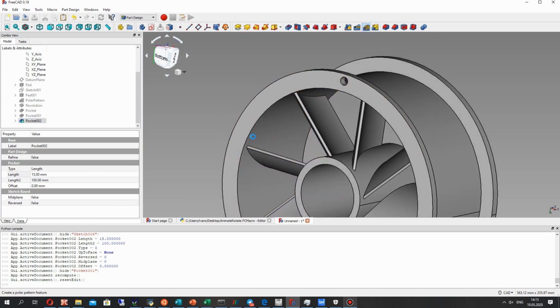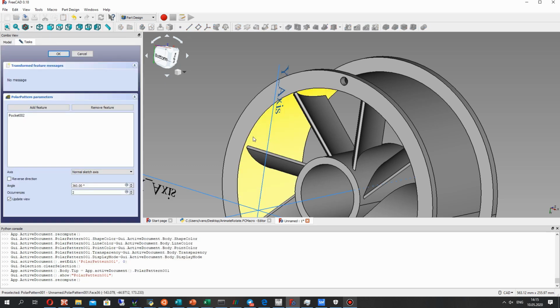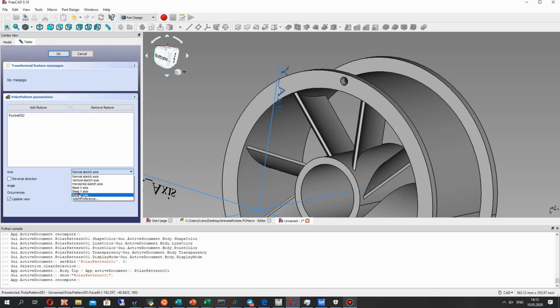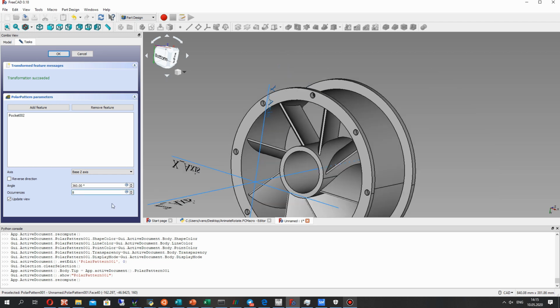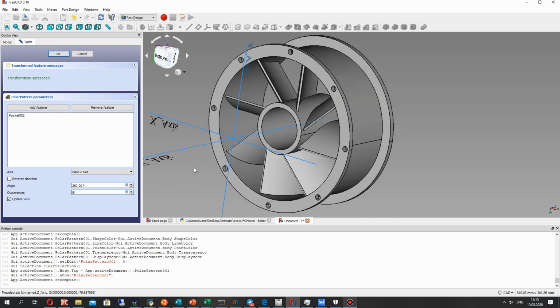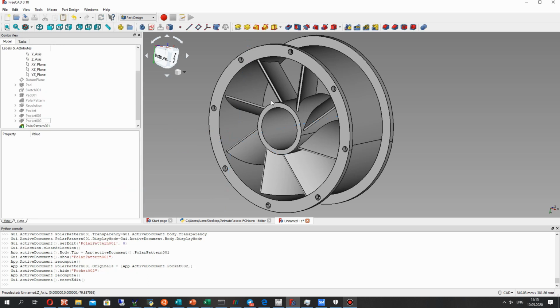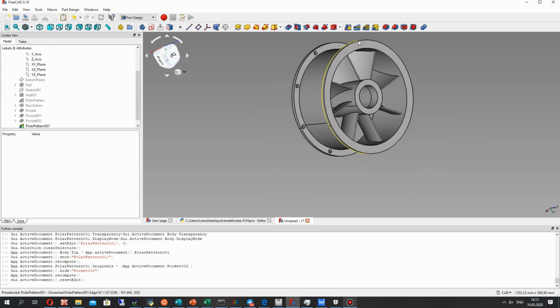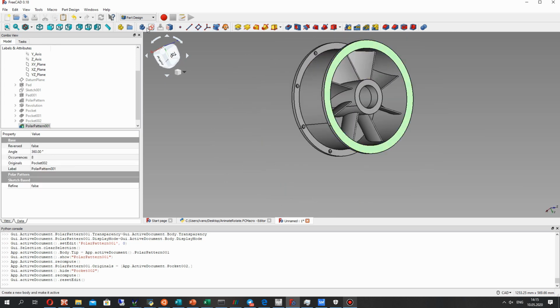And now we have created the polar array for our hole. For this we will be using the z-axis, it is the rotation axis, and set 8 holes for our flange. And we will repeat this operation for the other surface of our flange. Yeah, okay.